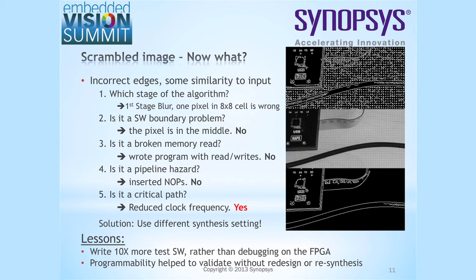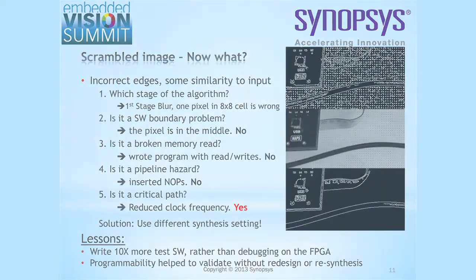And we're actually glad to have the programmability, because now imagine if this was a fixed RTL, which is also possible for a simple algorithm like that. If you want to get at the stages of the algorithm, it means resynthesis and a chance to also introduce new errors that are then harder to find than just making some quick software changes.